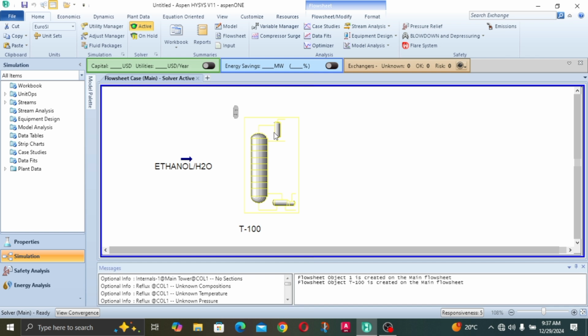As for the condenser, if by any chance a little bit of the second component follows the first component trying to be separated, the condenser does the condensing to bring it back to the bottom to have a better purity level at the top. So let's be more detailed about it.